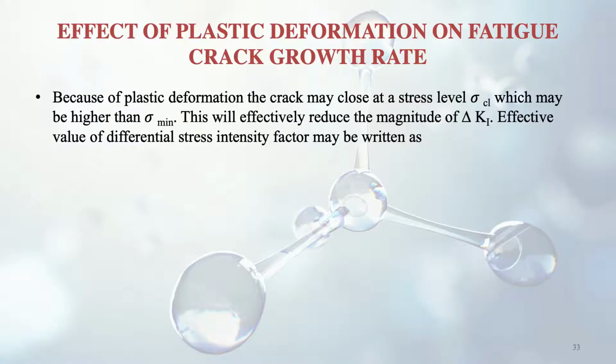Now the effect of plastic deformation on fatigue crack growth rate. We will discuss this now: how this plastic deformation will affect our crack growth rate in case of fatigue. Because of plastic deformation, the crack may close at a stress which is known as sigma CL, which may be higher than sigma minimum, and this will effectively reduce the magnitude of delta K.